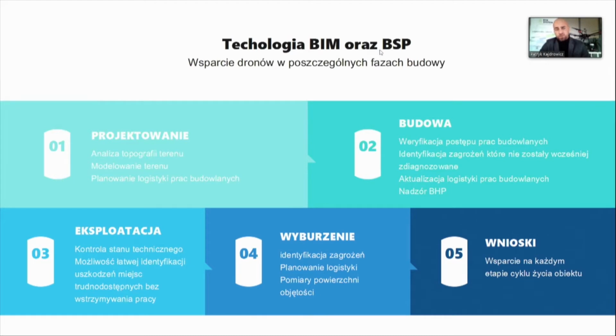And in the design phase, the use of drones in the construction industry has been widely tested. They are used for land surveying, for measuring of facilities, for historical areas, but also for difficult to access areas. And measurement of an area with a drone is based on photogrammetry, and you start with taking some photos, and they are processed with software, and as a result of the processing you get a dot cloud, and this can be further processed to create a network of mesh. It can be a basis to model a facility for the purposes of the construction industry, and from the cloud you can generate numeric models of terrain.